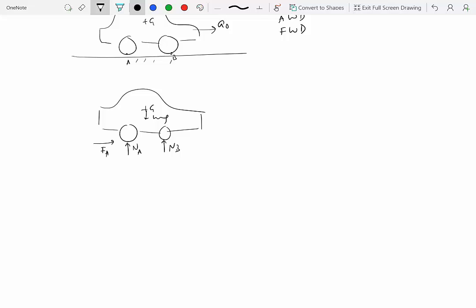But the front wheels are not powered, so the friction force on them points in the opposite direction. So the directions of the friction forces are different, even though the motion of the wheels is clockwise for both front and rear wheels, and they depend on which wheel has the torque applied on it. From the engine, there is a torque applied on the rear wheels that's making the car go forward. The front wheels are simply transported forward because the rear wheels are pushing them through the frame of the car. Those are the directions of the friction forces.